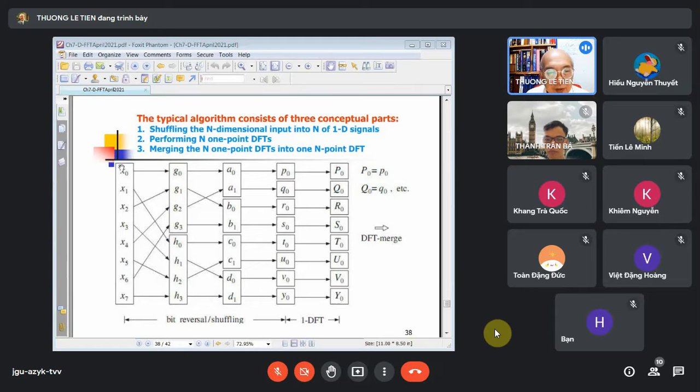For example, we have the input. We split it into couples: that is the even group, that is the odd group. Specifically for x[n]. And split them up again: even, odd, even, odd. This one shows you just splitting it into 1D signals. But actually we don't need to. Practically, we can directly calculate the DFT from 2D signals.